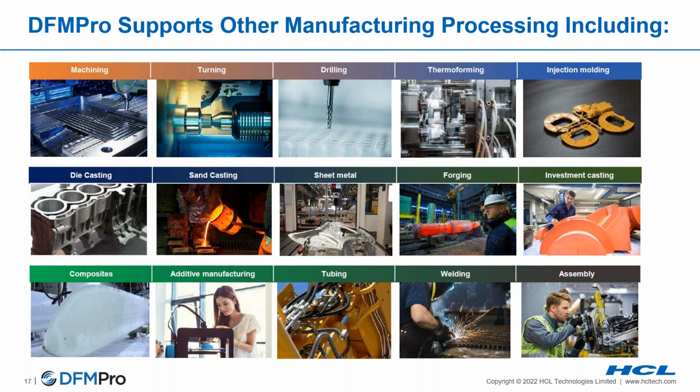Does DFMPro support the multi-body functionality that Creo Parametric introduced in version 7.0 and above? Yes, DFMPro supports the multi-body capability that Creo has introduced in 7.0 onwards. DFMPro supports sheet metal, injection molding, and additive manufacturing as multi-body design. In injection molding, one can run two-shot molding, over molding, multi-cavity molding, etc.